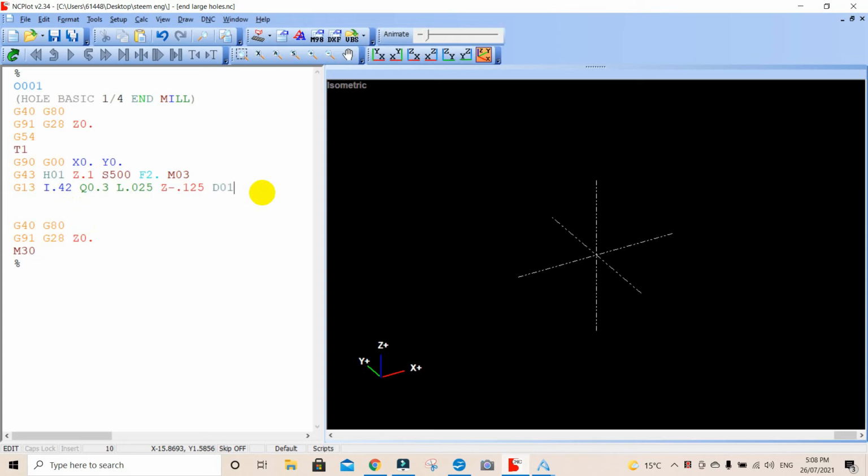The D is 1 or 0, 1. Doesn't really matter. This is tool number 1. D comp is the 1 as well. So the height of the tool is set. Where's our height? There's our height. It is tool number 1. The D comp is the radius of the tool, also referring back to tool number 1. That should do something. Let's give it a go.